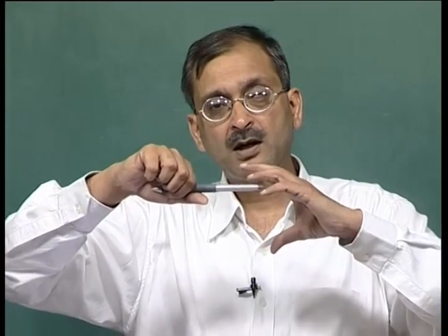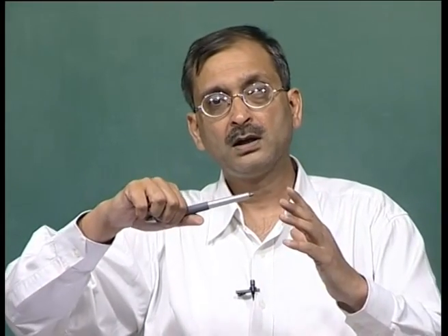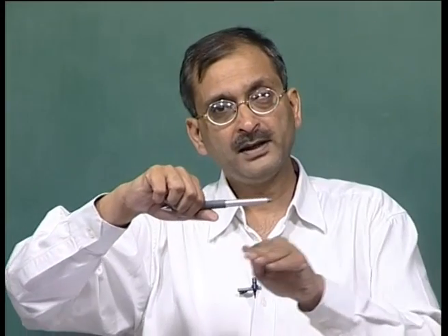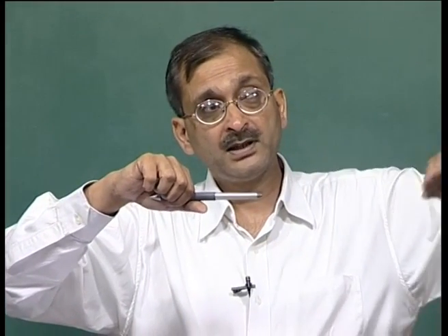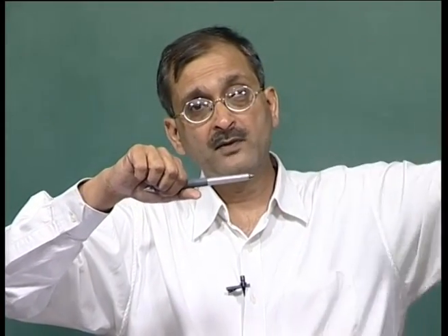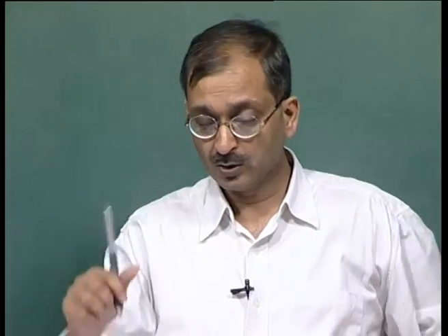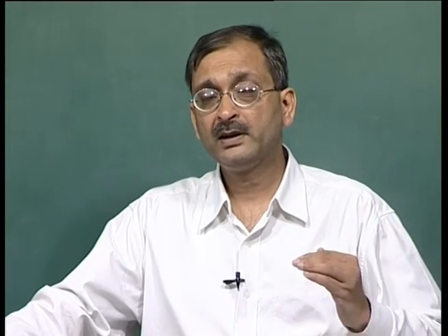Then this confined aquifer is no longer confined, because the water here is at the atmospheric pressure, because it is related to the atmosphere somewhere from the recharge area. So, the confined aquifer actually becomes unconfined if the piezometric surface falls below the upper confining layer.